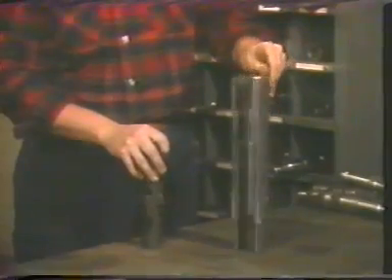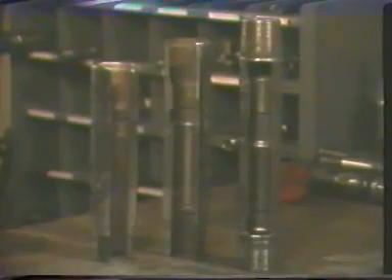These landing nipples are designed to permit specific locking mandrels, nipple locks, to be installed in the nipples. Most subsurface controls are installed using this equipment. A landing nipple is a short section of pipe which is threaded on each end and installed as part of the tubing string during completion of the well.